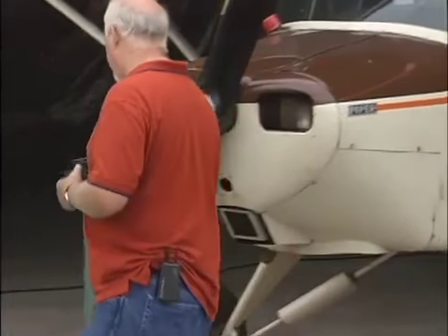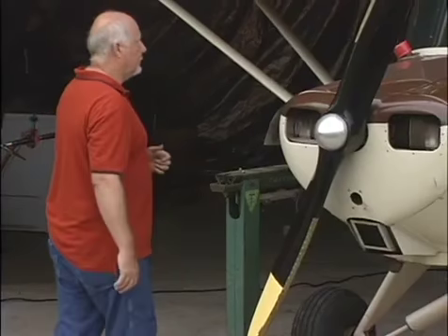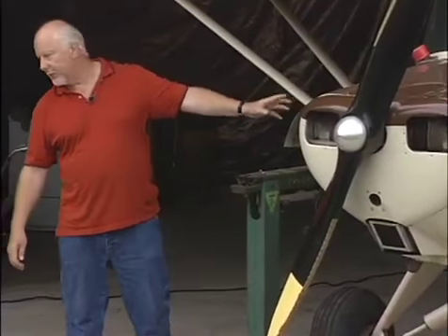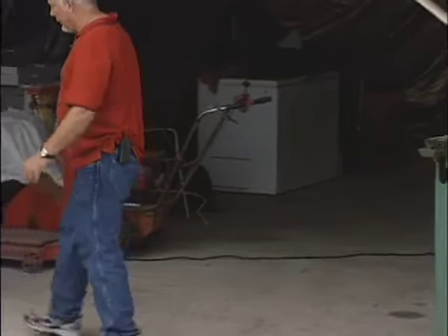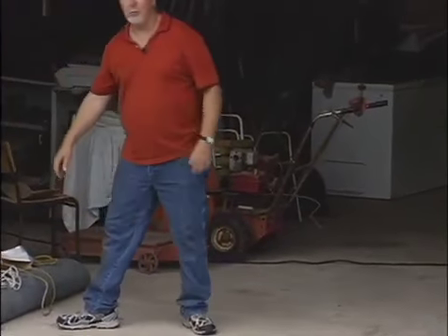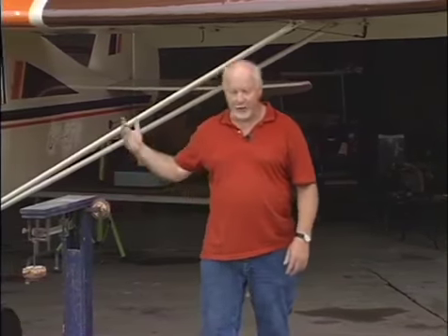Another thing to think of when you're doing the weight and balance is you want to make sure that everything is cleaned out of the airplane. For instance, this aircraft had some tie-down chocks and some ropes and stuff in the back. You want to clean everything out. You want the aircraft to be as clean as possible when you're going to weigh it. Because quite often aircraft are designed that if you fill them full of fuel, in this particular aircraft you can carry a passenger. If you put a passenger in it, it also has a baggage compartment. You fill the baggage compartment to its maximum capacity, you can overload the aircraft.